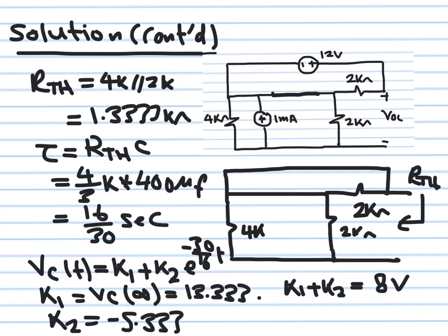In order to calculate it, you have to make this one short circuit, you have to make this one open circuit, and this is how the circuit looks. If you take a look at this circuit, you will see that we have this short, and this eliminates the 2K, and really the input resistance R Thevenin is 2K in parallel with 4K. So 2K in parallel with 4K is 4 by 2 over 4 plus 2, so it's going to give you 8 over 6, so it's 1.333 kilo ohm.